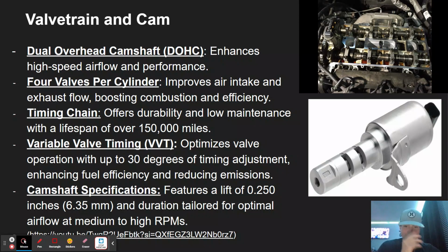Going back to the valve train, this engine employs advanced variable valve timing technology, or VVT, which allows the timing of the valve opening and closing to be adjusted dynamically. This adaptability is crucial for balancing power output and fuel efficiency across different driving conditions. In this engine, VVT can adjust the intake valve's timing over a range of 30 degrees. This flexibility helps in reducing emissions and improving fuel economy.